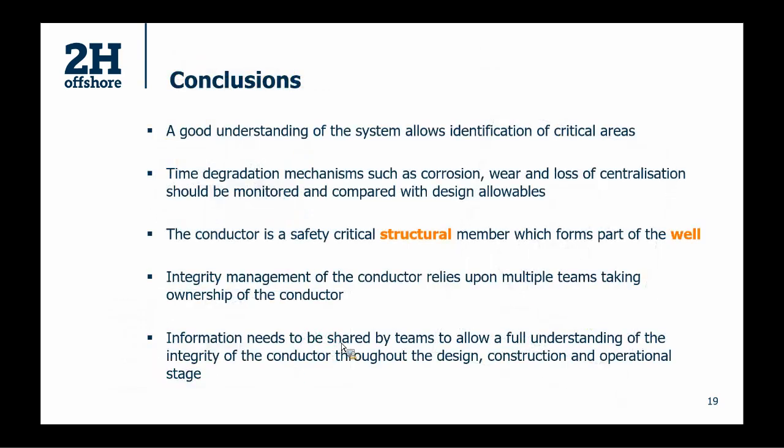So just to conclude, the best way to manage the integrity of the conductor is to have a really good understanding of the system, know where the critical areas are, and also know which parameters are going to have the most effect in changing that response. Things like corrosion are going to occur and there's not really a lot you can do about them. You can make sure that your system is designed to accommodate for them, and then all you can do after that is to monitor it and compare it with the design allowables that the system has been designed to withstand.